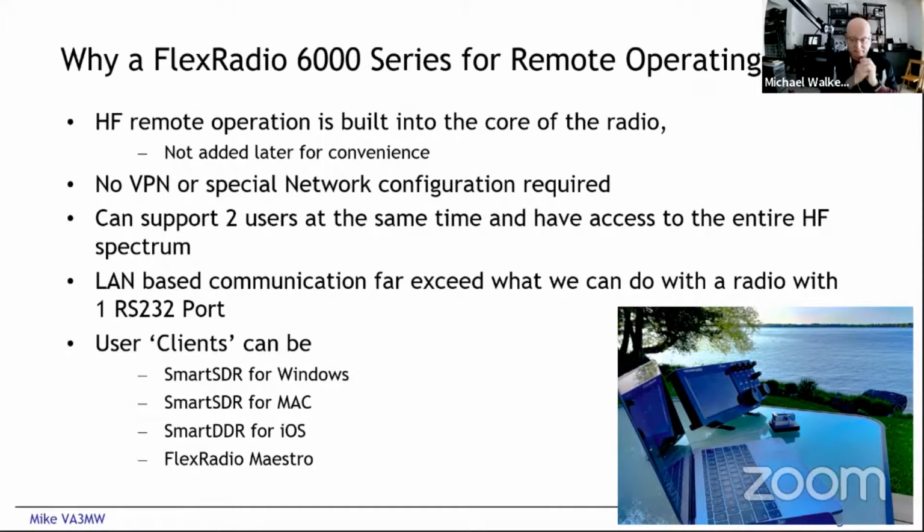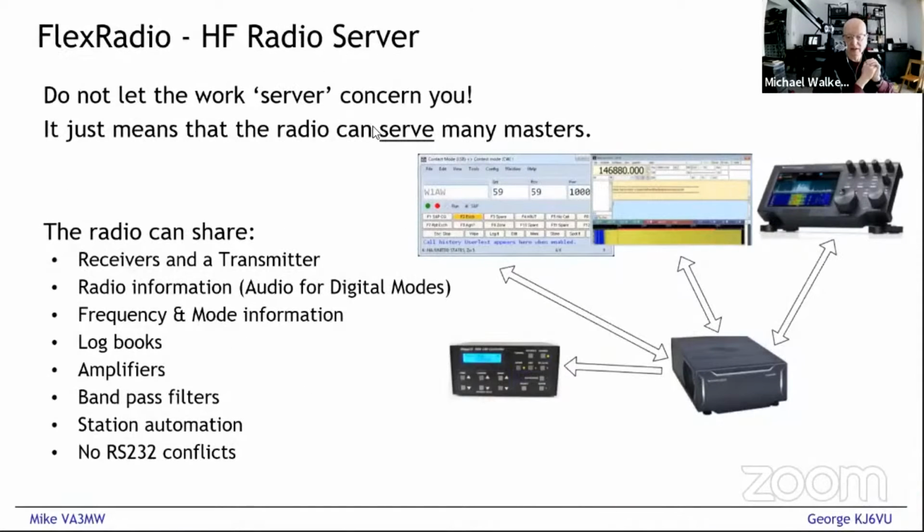Next slide, please. So this is sort of the quick view. Now we have a radio sitting in the bottom right. It's either in front of me, or maybe it's at the base of the tower. I tell you what, Cat 6 or 5 cable is a lot cheaper than 4 runs of LMR 400 or better. And it's also just sort of the way we're heading.